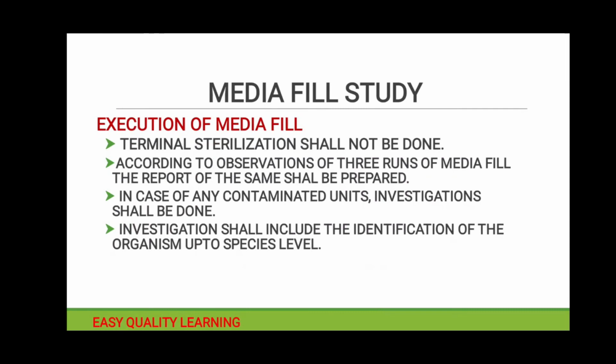Something we need to remember is that if our product has a routine terminal sterilization cycle, then it shall not be considered during the media fill activity, because if we do terminal sterilization, we will not be able to find contamination, if any, during aseptic processing. So this step shall be avoided if it is there in your commercial production cycle.